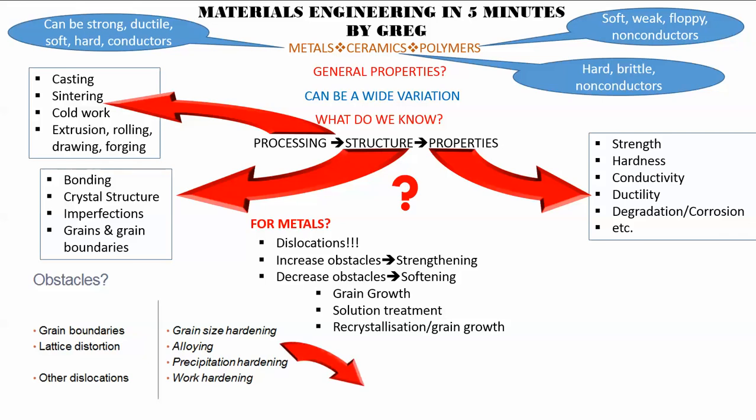Of course, with alloying and precipitation hardening, we use phase diagrams. We looked at phases, we looked at lever rules, or more precisely the inverse lever rule. We also looked at microconstituents. It's very important not to confuse microconstituents with phases. The phase diagrams give us an idea what happens under equilibrium cooling, but we also looked at non-equilibrium cooling, and